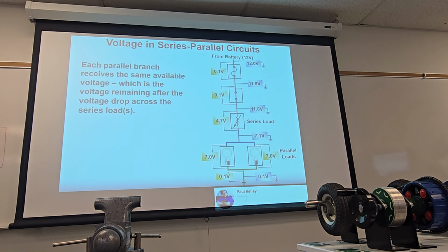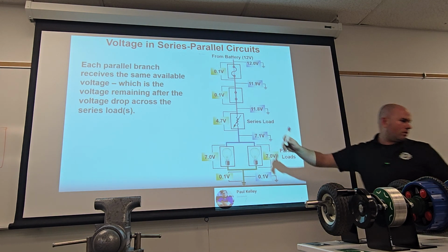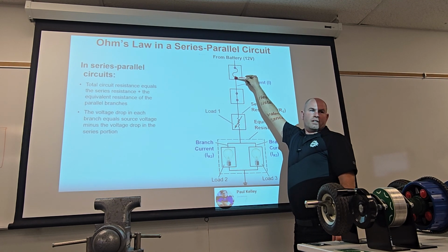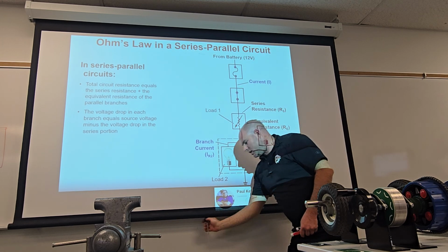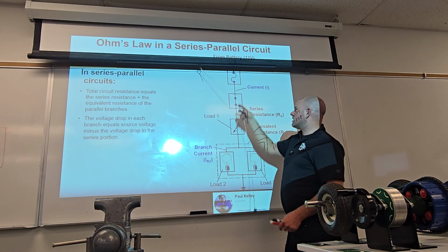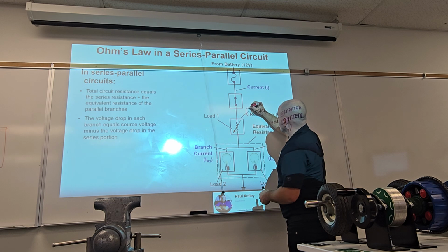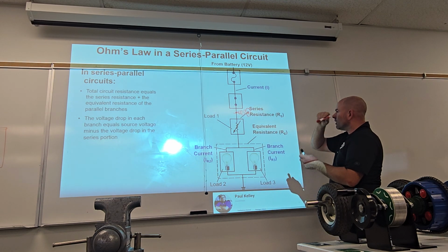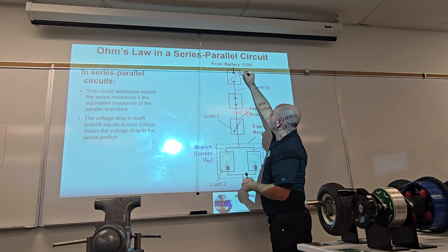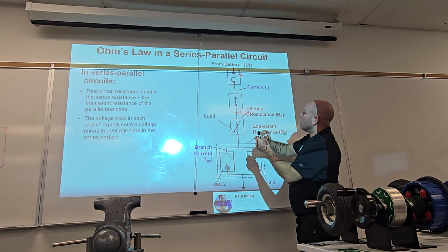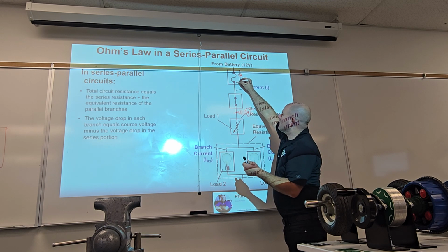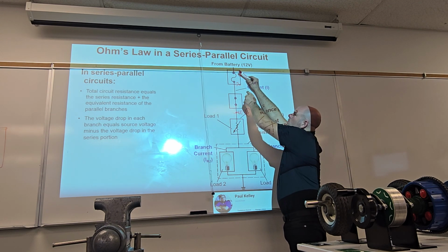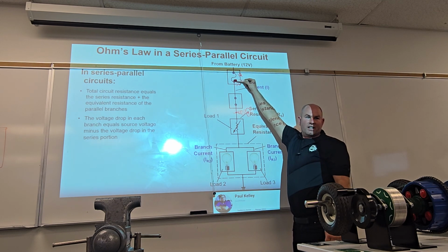Okay, so if I were to take the fuse out, one more. This fuse should have 12 volts and 12 volts, right? But let's just say Sparky sent the screw in here. Remember this screw? Bzzz, like that. Sparky sent the screw in there. Now this has 12, and if this is grounded, what do we have right there? Exactly. So if I take the fuse out and put a bulb in, the bulb will light because it has 12 volts and 0 volts, right?